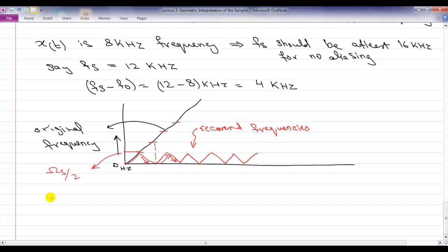But aliasing is bad because that same frequency turns up as a different frequency in your system. So not only do you not recover that frequency, you get something that was never present in the signal. So at the very least, you want to avoid this aliasing. If you can't recover that higher frequency, let's not do that, but don't make it appear as something else.